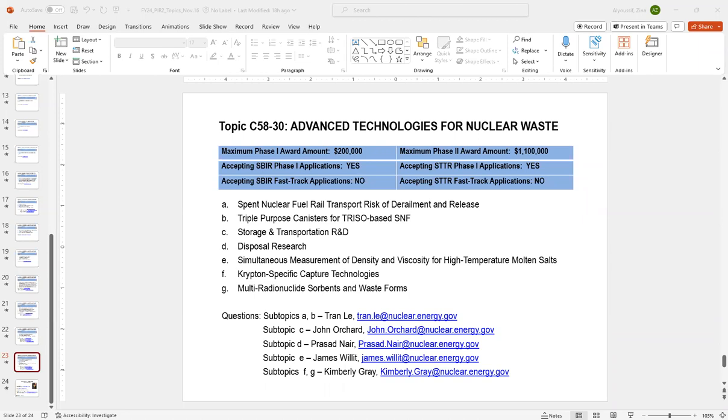We have, on site at a lot of the reactor sites, many of these dry storage casks sitting there. They are welded structures, about 5/8 of an inch, 304 stainless steel, with a concrete overpack. It's all licensed under the storage requirements, but it was estimated that they would stay for about 40 years. Now, with the change in the overall strategy, we are looking at them probably staying for more than maybe 100 years.